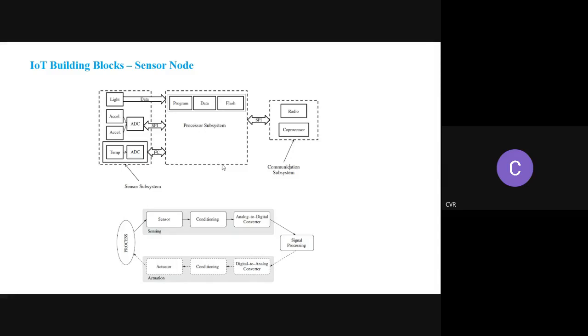Okay, so one is to control, then you need to acquire the data. The data can be acquired in different ways. It could be through I2C or SPI, or maybe you can acquire the data directly. If it is analog data, you can connect to the analog to digital conversion port of the processor and so on. Okay, so you'll have memories to store the data and so on.